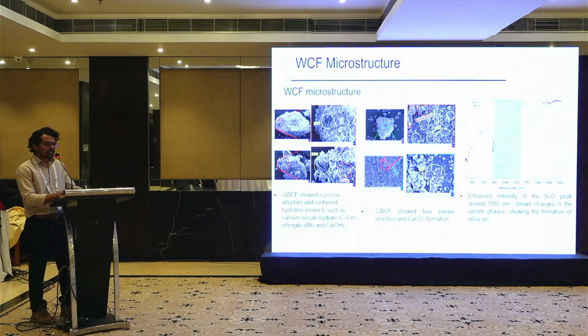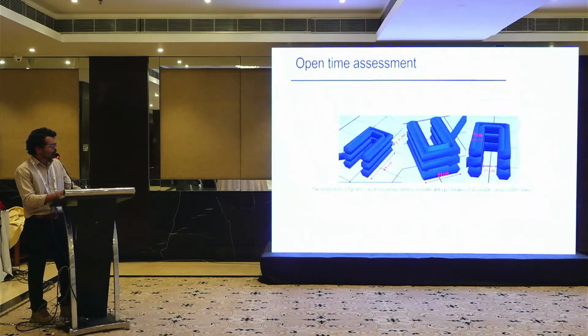This is the microstructure of the waste concrete fines before and after carbonation. After carbonation, it showed a huge amount of calcium carbonate together with aluminosilica gel, which is reactive in nature, and the same was observed from the FTIR also.